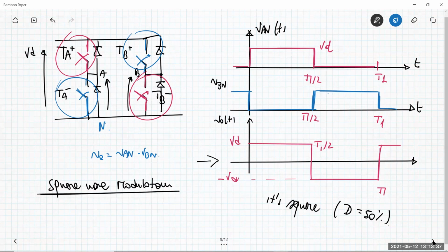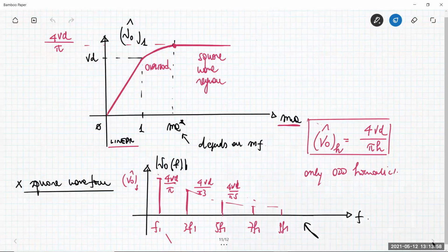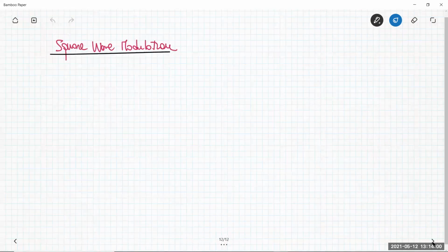Okay, no more than this. There is no need of a control voltage, you don't need any triangular waveform, etc. In terms of generation, it is very simple. Simply switch on and off the pairs of switches that are indicated there with this frequency. So basically this is no more a pulse width modulation.